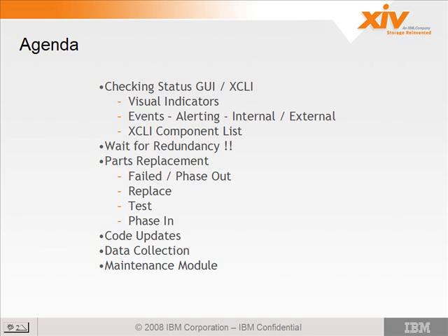Well, that's why you should never do a dummy replace on a component. You always replace it. If you test a component that has failed without replacing it, like you said, it may come back and function, but then it has the probability of dying once again. So anything like a module that fails, you definitely want to make sure you replace it and not just do a dummy replace and bring it back into the system.